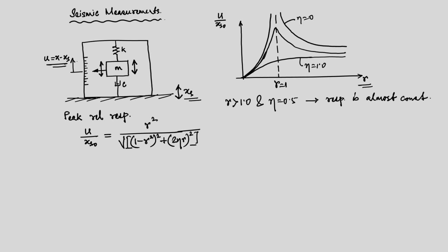Now, if the response of a properly damped instrument becomes constant, then in that case the relative response u is directly proportional to the base displacement.